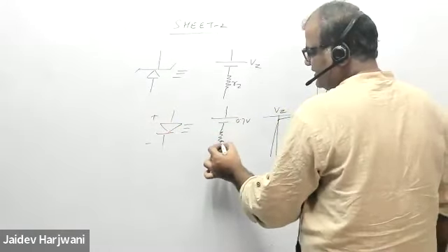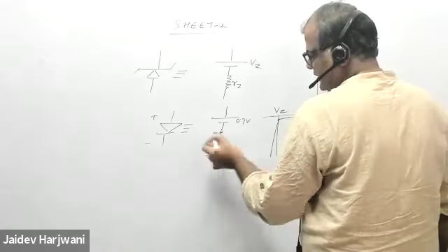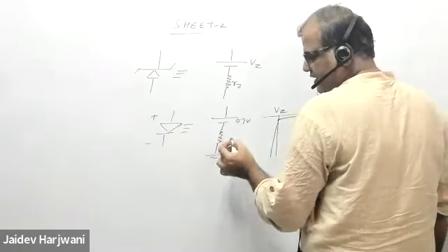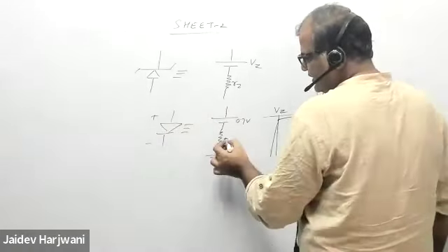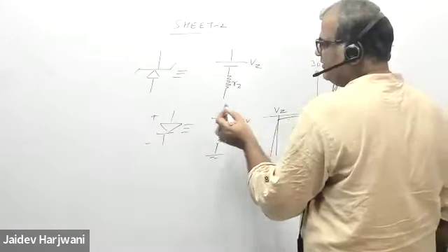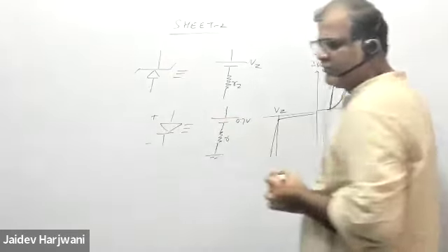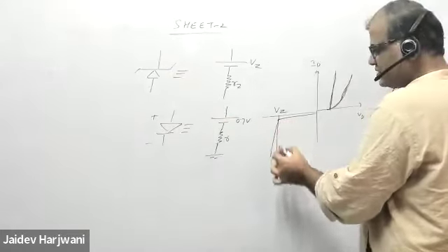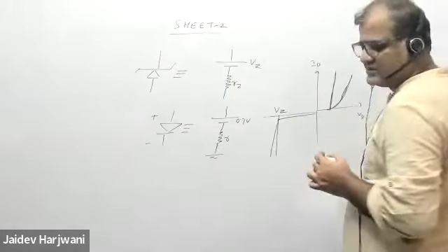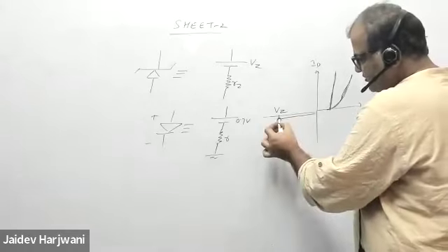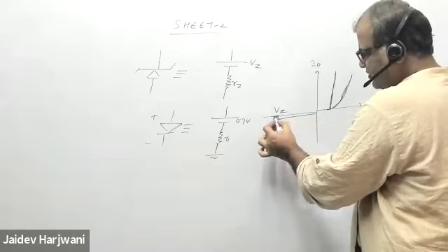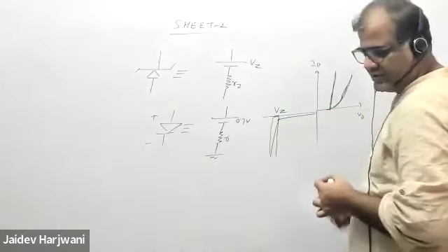And sometimes we say there is a resistance also in the piecewise linear model. In the constant voltage model, I say this is 0.7 volt, and when I use a piecewise linear model, I say there is some resistance also involved. Similarly here in the reverse bias, because it's the voltage regulator, generally the voltage is fixed across the Zener diode in reverse bias, but now I'm putting a resistance also. So the actual characteristics will be like this: some resistance variation, some voltage variation will be there from here to here across the Zener diode.